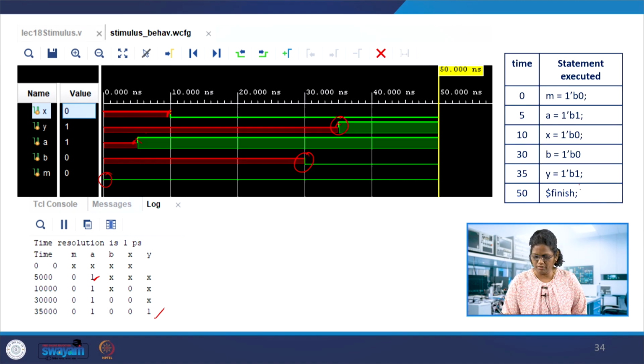I have given this already. So with this we have seen the blocking and non-blocking assignments, how the swapping example works, the immediate assignment and late assignment. We introduced blocking in the previous example, with the blocking assignment and timing control, and saw how the simulator moves and keeps track of time for the statements to be executed.